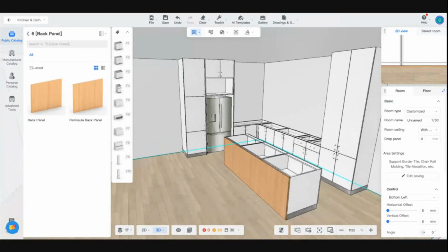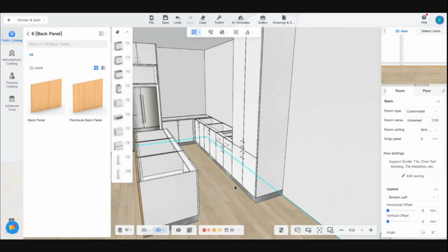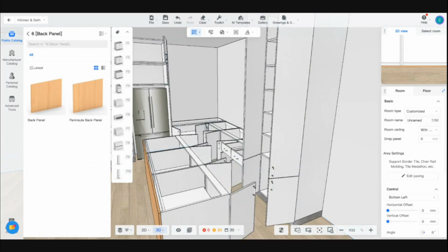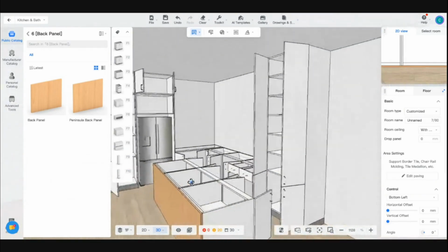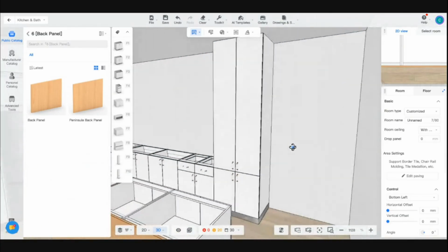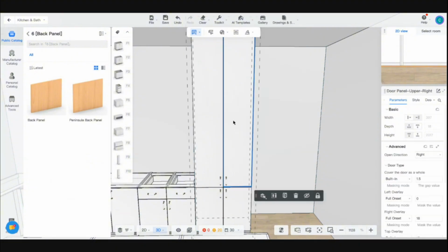Okay. So the next step, if you want to confirm all the openings of the doors, you can also use Control O or Command O on your Mac. So just click it, Command O, so all the doors will be open, like this one. Okay. You can change all the openings. For example, I'm going to show you, like this one. If I want to change this opening door,